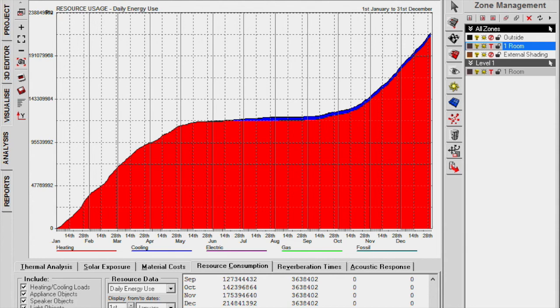So 256 to 214. In terms of the total amount of heat consumed by the building, by shifting the set point down, 2 degrees or 4 degrees, something like that, I was actually able to lower the consumption of the building. It's not exactly a fifth. It's not too bad, probably about 15%. So there are different things we can do to the building, one of which is playing around with your comfort zone. But that's not necessarily the best way to do it. Let's talk about other ways to do it. We actually get into the notion of the building envelope and how we adjust that.